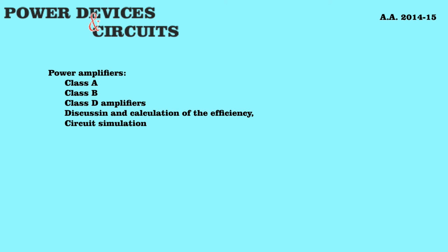It's not the maximum. The problem here is you can see a number of pulses for the current. Here you have this peak. These are exactly the periods in which, notwithstanding my effort to avoid them, the devices still conduct a bit together. And you have this short circuit. If you fail a bit with the sign, the efficiency drops dramatically.